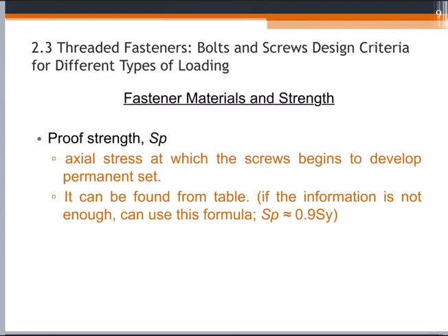In order to find the value of tightening torque, total force on bolt and parts, also the factor of safety and the stress values on that screw, there are some values we need to find. The first value is the proof strength, Sp.